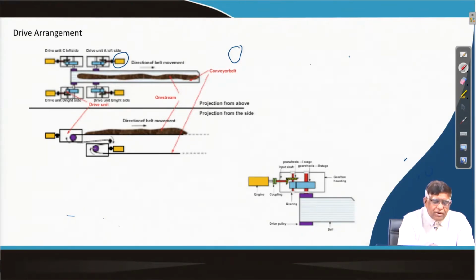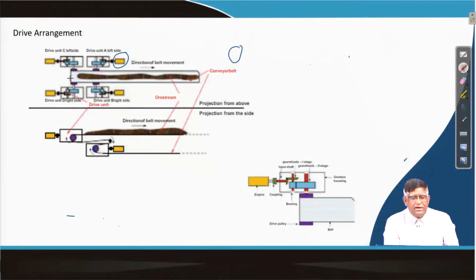So you have this driving drum, and the two end pulleys are driven over here. Alternatively, there could be an electric motor at only one end. From the electric motor you run a gearbox, from the gearbox shaft you give a drive to this gear, the pulley is rotated and the conveyor belt runs. So this is a single arrangement, and here we have a drive pulley.